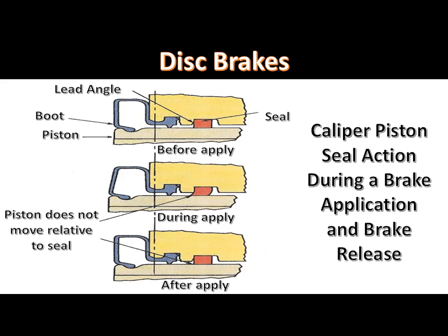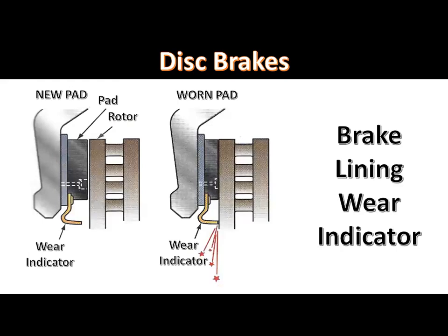These brakes do not experience brake fade because as the rotors are heated, they expand and move slightly closer to the brake pad linings. These brakes do not provide any servo action. Many disc brakes have a wear indicator attached to one of the brake pads. When the brake pad lining wears a specific amount, the wear indicator contacts the rotor, causing a scraping noise that alerts the driver about the brake problem.